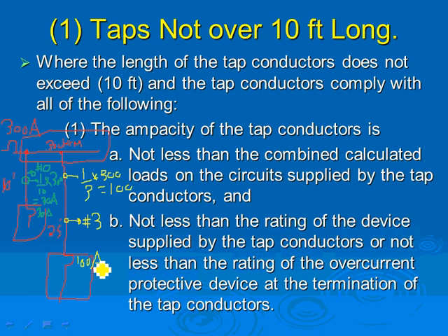What's the disadvantage? Any ground fault or short circuit here on the line side of all this equipment could easily trip your main. The 25-foot has to be in conduit also. Yes, full protection, so you have to protect them in a conduit, the 25 as well as the 10. Put them in a conduit. I think your code even says metal.